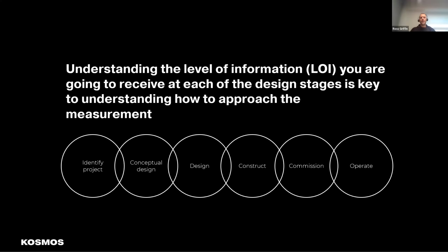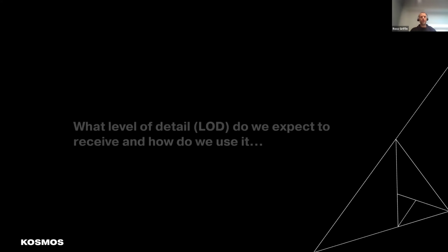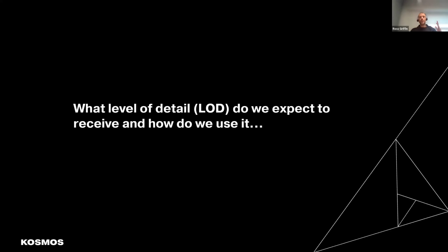So LOI and LOD, level of information, level of detail. We've already agreed this in the BIM execution plan. So we'll know what we're talking about, but it's important again to refresh, because obviously the design gateways are a period of time, and you might remember preparing the BIM execution plan 3 or 4 months ago, but now you're bringing new team members into the team. They might not know it. They might read it and still not understand it. So having these refreshers at the stages to understand the level of detail and level of information is quite important, I would say.